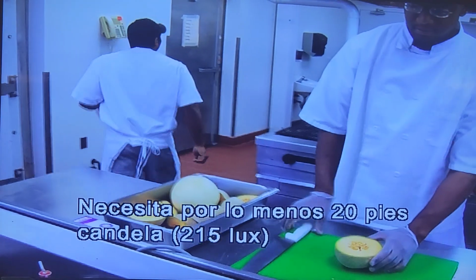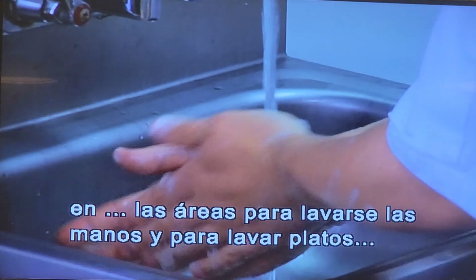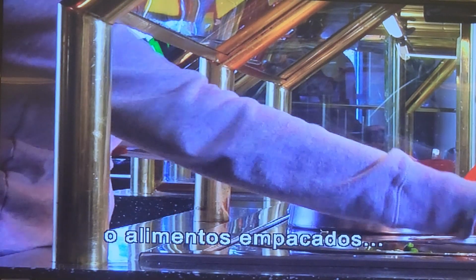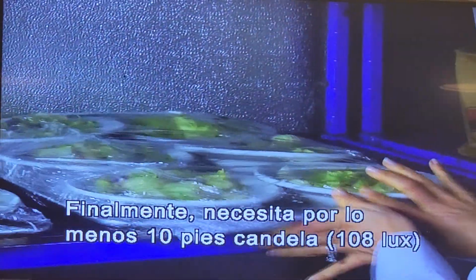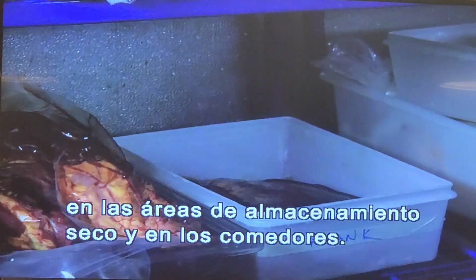You'll need at least 20 foot candles, 215 lux of light, in hand washing and dishwashing areas, buffets, salad bars, and displays for produce or packaged food, in wait stations and utensil storage areas, in restrooms, and inside some equipment, such as reach-in coolers. Finally, you'll need at least 10 foot candles, 108 lux of light, inside walk-in coolers and freezers, dry storage areas, and dining rooms.